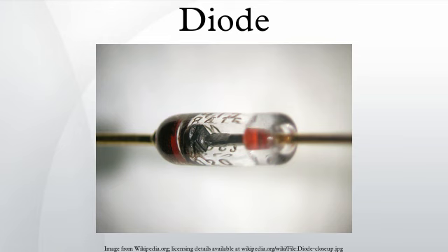Schottky diodes. Schottky diodes are constructed from a metal to semiconductor contact. They have a lower forward voltage drop than PN junction diodes. Their forward voltage drop at forward currents of about 1 mA is in the range 0.15 V to 0.45 V, which makes them useful in voltage clamping applications and prevention of transistor saturation. They can also be used as low-loss rectifiers, although their reverse leakage current is in general higher than that of other diodes.